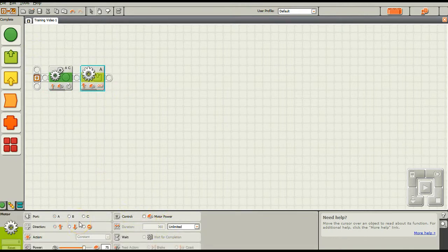Now again, depending on the width or size of your robot, I want to make a right-hand turn, so I'm going to use my left motor, which is my A motor. We're going to tell it to go forward. Same thing, 50 speed, because we don't want to go too fast. All right. And what we used in Kings of Construction was the belief that it was a 270-degree turn. But again, that was the basis of our wheelbase. Yours might be slightly different. That you have to kind of figure out through trial and error, kind of mark your robot, and we can figure that out. And I'll show you guys some neat tricks during practice to be able to do that. All right. Now, so I've got a robot that goes forward and turns.